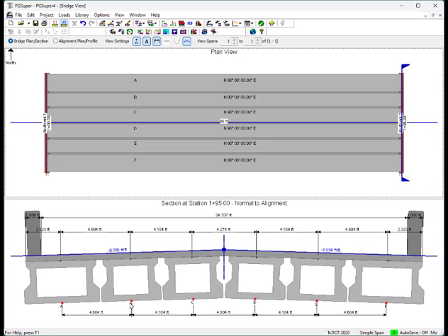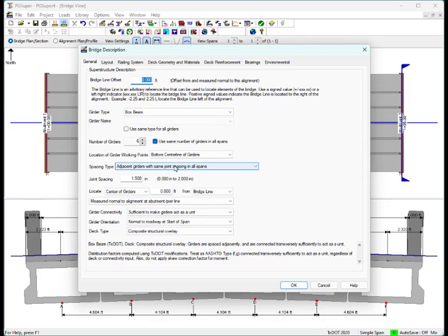As we mentioned, the work points are at the bottom of the girder. The spacing is 4.104 feet, which is equal to 47 3/4 inches plus our 1.5 inch joint spacing. As you can see, the input joint spacing causes the values at the bottom work point to be exactly what's specified. Here at the top, our spacing is wider because of the change in angle at the crown point. Let's go ahead and move the work point to the top of the girder. So here we go, working point at top center line of girders.